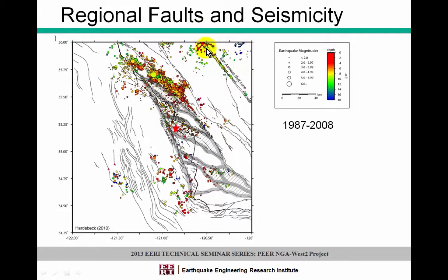And then in the upper right-hand part of this figure, you'll see the San Andreas Fault mapped out with the tightly clustered seismicity. And this little clustering that starts to just go off the edge of the plot, that's the much anticipated Parkfield event, the magnitude 6 event that finally occurred in Parkfield. So you can see that for Diablo Canyon, you're not relatively close, but you do have a lot of seismicity in the area. The distance from the plant to the San Andreas Fault is about 80 kilometers, just for reference. And then you can see you have some associated seismicity off the coast and also some mapped fault traces throughout the area.